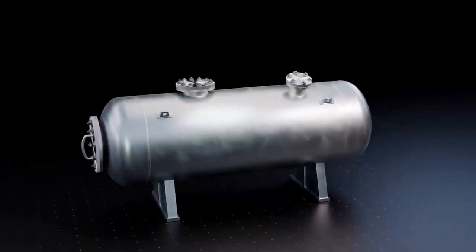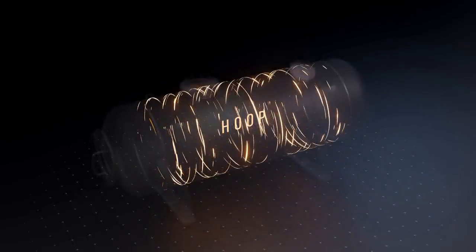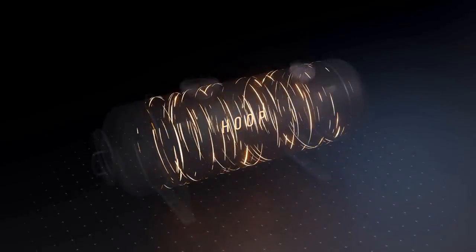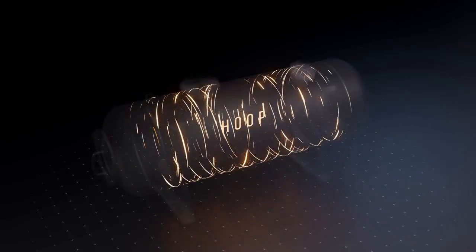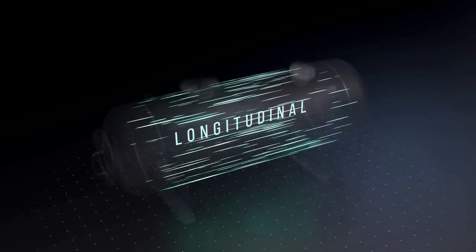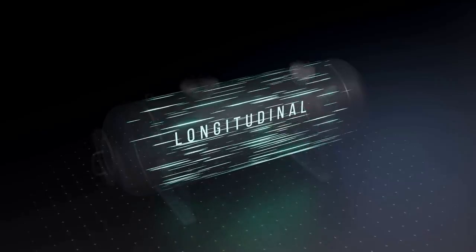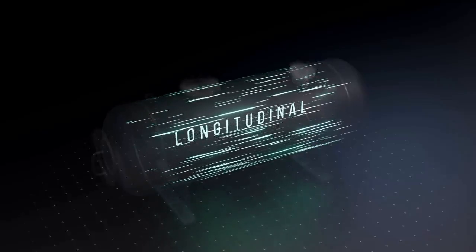In the hoop direction, around the circumference of the cylinder, from the pressure trying to radially expand the circular cross-section, and in the longitudinal direction, from the pressure pushing against the ends of the vessel and trying to stretch it along its length. Being able to quantify these stresses is the key to safely designing pressure vessels.